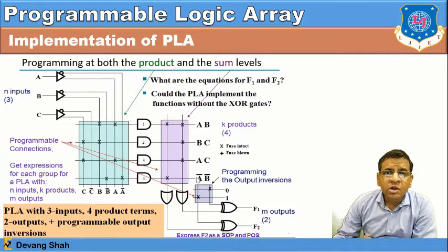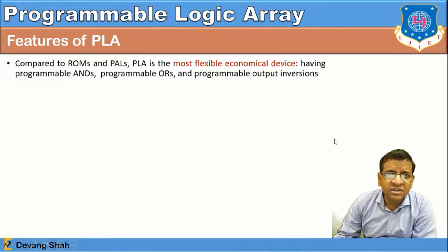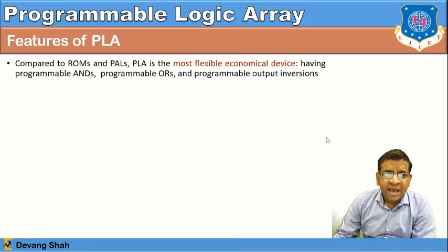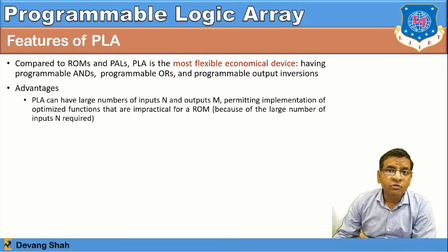You get more flexibility in making the logic of Boolean functions, right? Based on that, we just discussed the features of this PLA. Compared to ROMs, PALs or PLAs are the most flexible economical devices, as I have discussed, having programmable ANDs, programmable ORs and programmable output inversions. That's what we have just seen in the first slide.